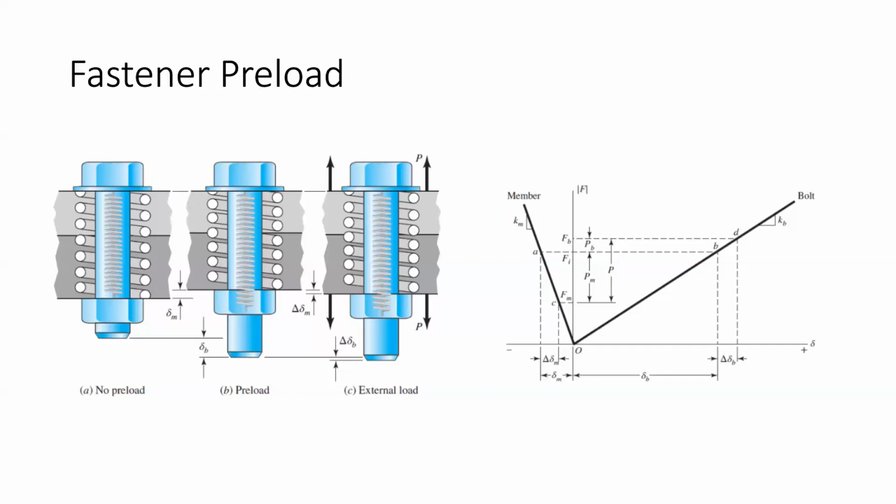There are some vibration measurements that you can do where, for example, you vibrate the light gray material and measure how it propagates to the other end of the fastener. And because the vibration propagation is dependent on the amount of stiffness or preload that you have in the system, you can actually assess if your system is still properly preloaded. And this is actually a really large area of acoustic analysis that you see in manufacturing warehouses. Sometimes they'll even have microphones just near a machine, and if they hear a slight difference in the frequency distribution, they'll be like, oh, something's wrong. And typically, more often than not, it's a fastener that's unloaded.